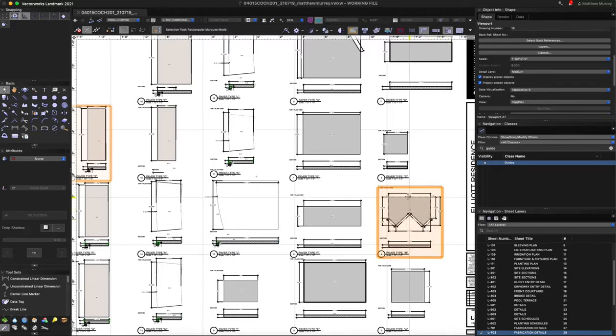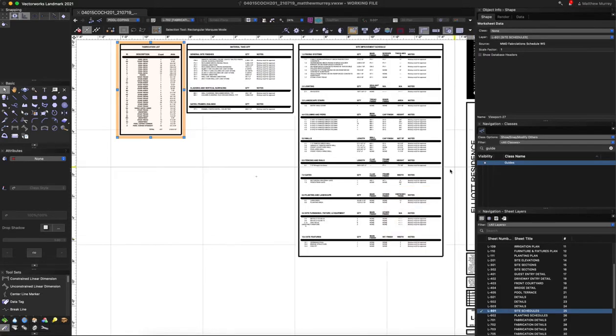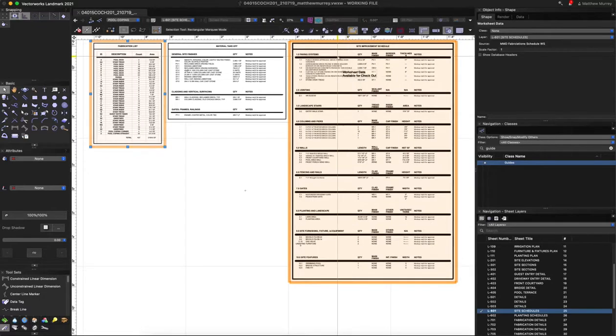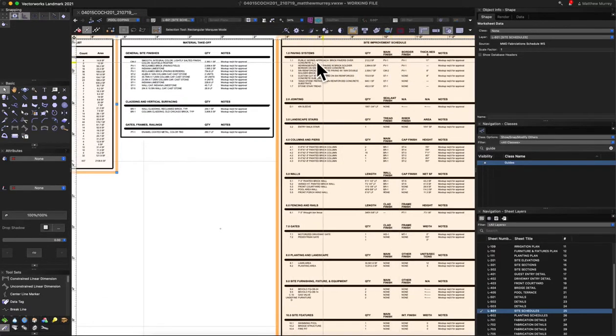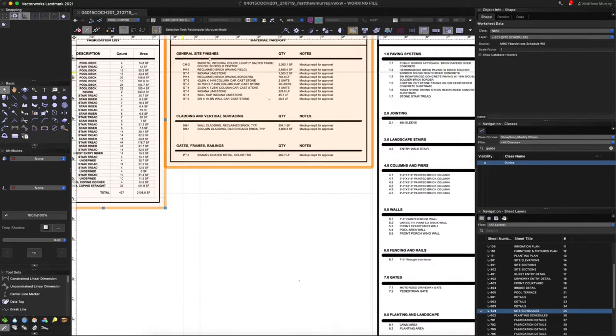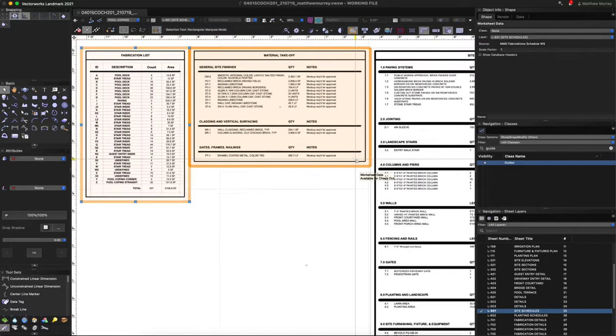Actually, first, I want to take you to our schedule sheet, because that can be really helpful for this too. So going back to our site object ID, this is how we use that data. This is the identifier and the description, and then we pull quantity and the finishes that are applied to it. We then take all those finishes and it adds it up here so that we know exactly how many square feet of such finish needs to be ordered for a project.